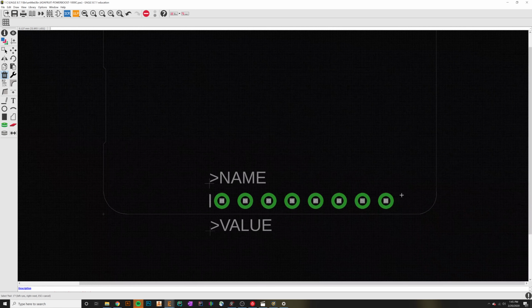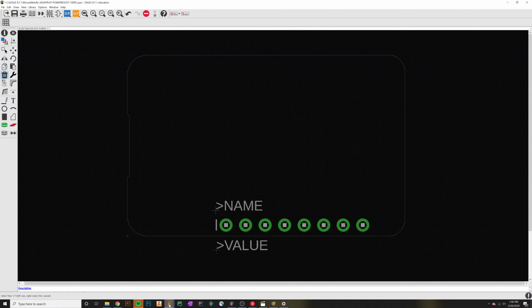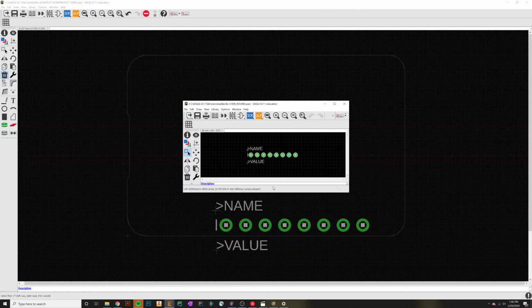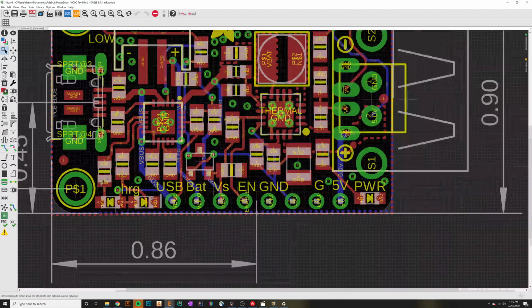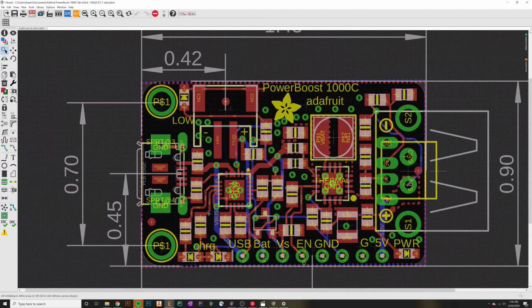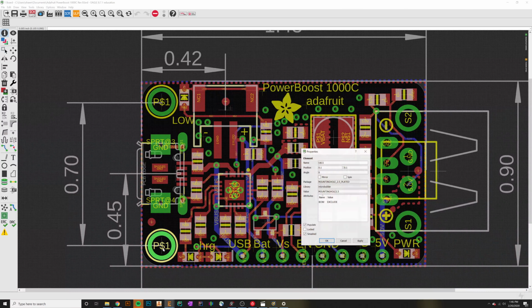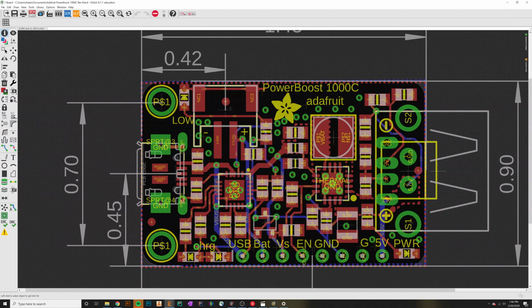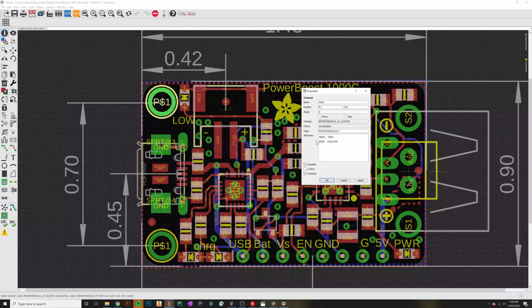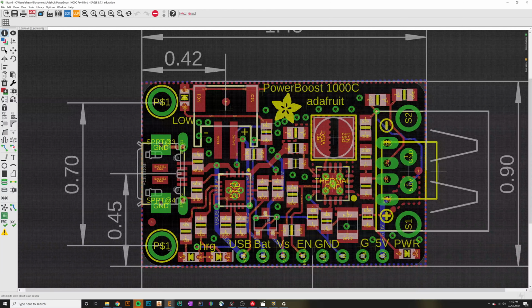Okay, and the next part you can do is actually add in the holes located on our other board here. So you notice that there are 4 corresponding holes for this board. And so what we can do is, if I click on here, this tells us that the holes are 2.5 millimeters. So you can see that 2.5. And apparently I can't click that one, but that's a part of the USB, so that makes sense. So I just need to add these two 2.5 millimeter holes, and I'm going to take note of their positions in the X and the Y.